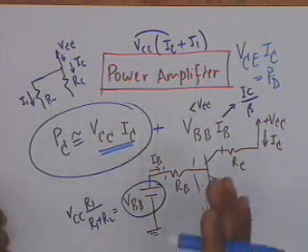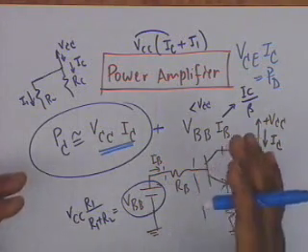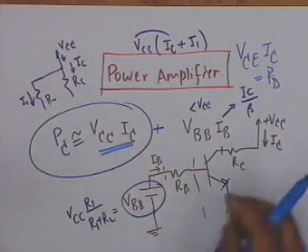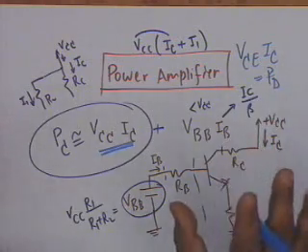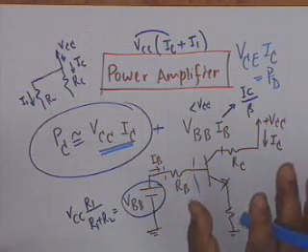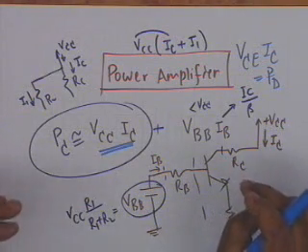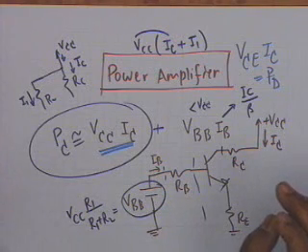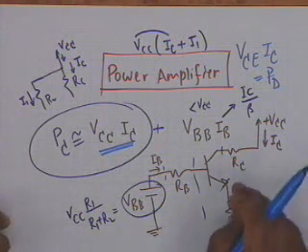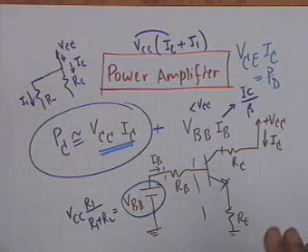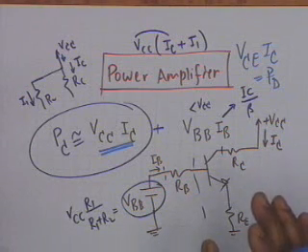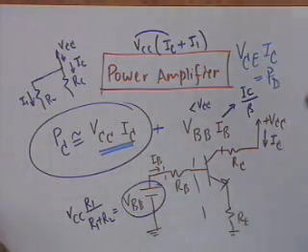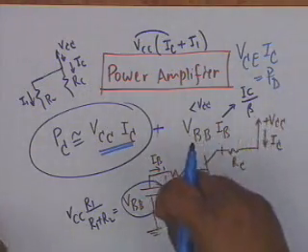On the other hand, if it is a voltage amplifier, all that you want to do is to have a large voltage gain. And you will see later that voltage gain simply depends on the resistances. It does not allow the currents and voltages to have very large swings. It is not required for large voltage gain. Similarly, for large current gain, large swings of current or large swings of voltage are not required. What is current gain? Output current divided by input current.